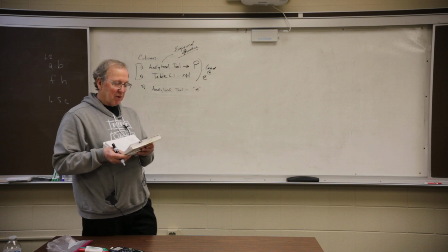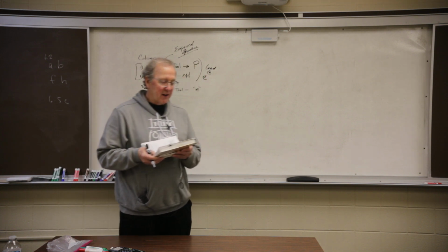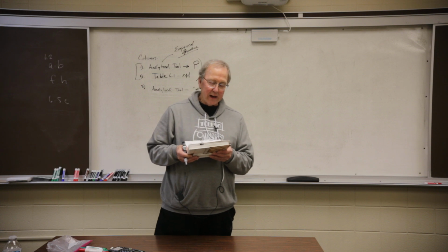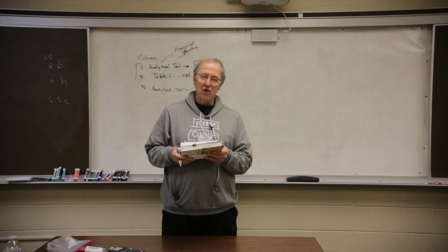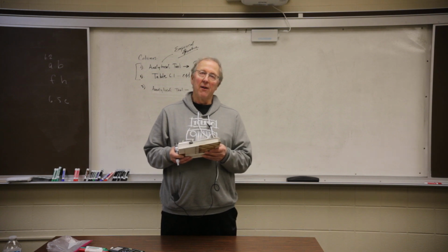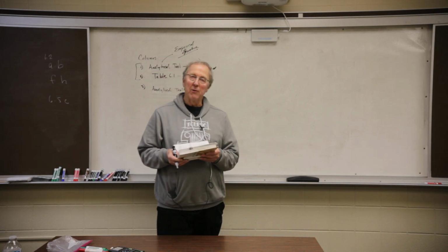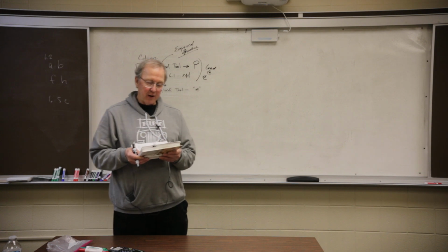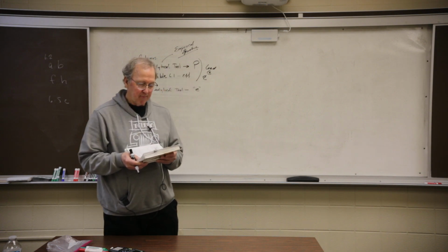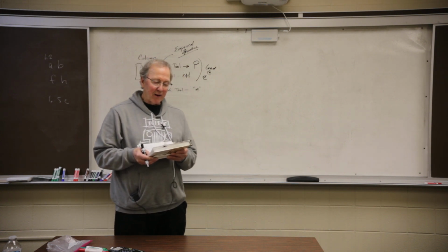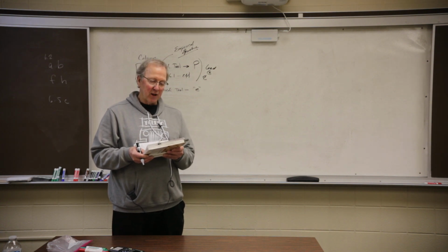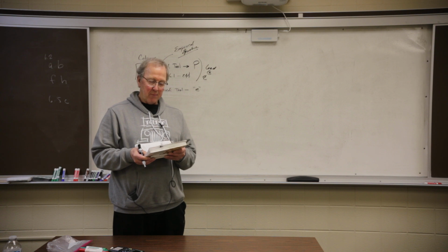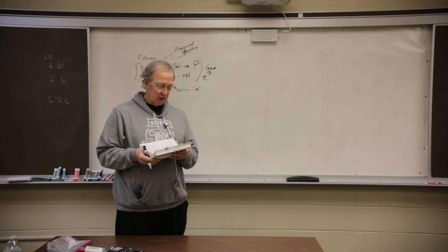If you look at that table, it's got nominal size, it's got the area. We would use area in our class to find out which is the least expensive. The least expensive is, of course, the one with the least area. There's the unbraced length, okay? In the field, it is the amount of load that particular member can carry at that particular unbraced length. But you got to remember this, look below it.